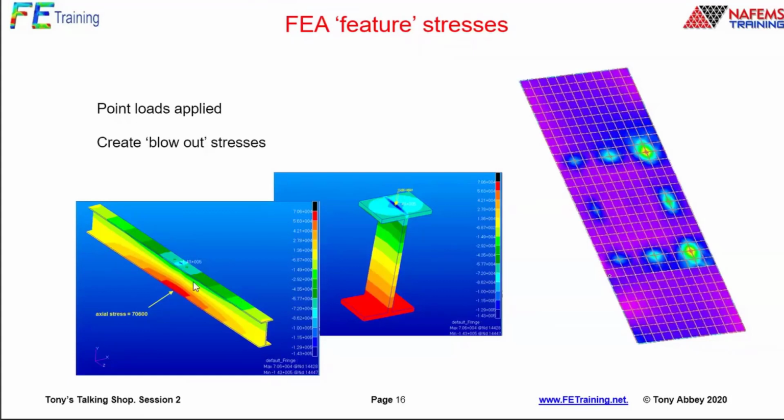This is an I-beam, and we do this in the Intro to FEA class, where I just put a load in the middle. And this is a direct axial stress running down in here. And it's building up. This is the actual triangular bending moment distribution building up, and hence the stress builds up in the same way. We expect to get extreme fiber stresses top and bottom the same. They are not at the top here.